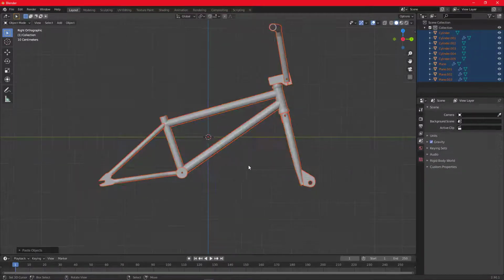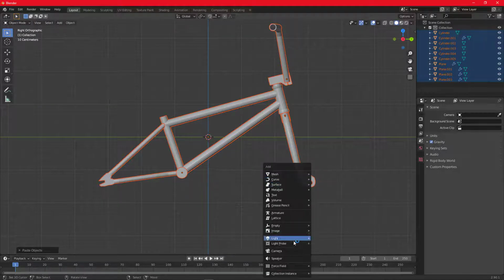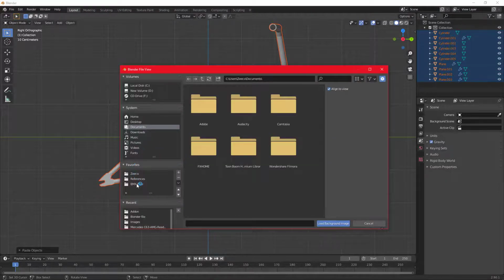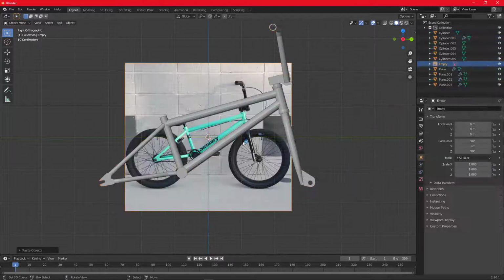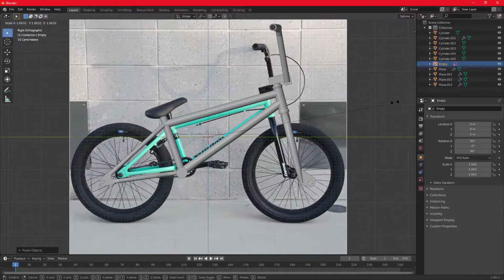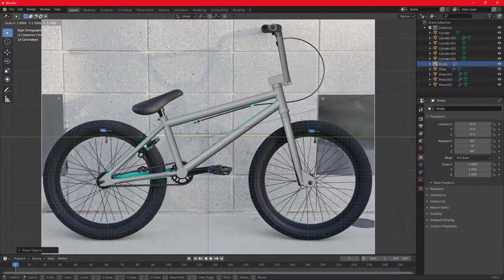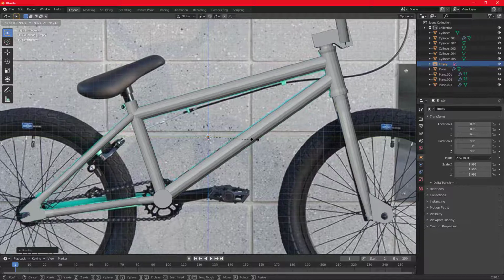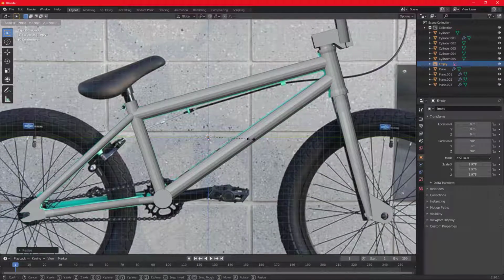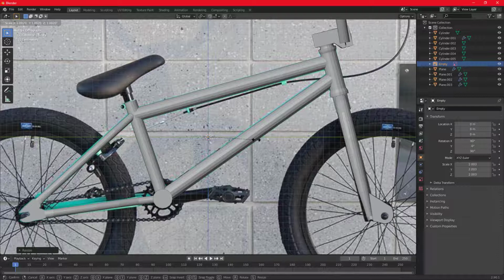and we continue with this and press Shift A, sorry, to add a new image, which is background image, and go to where you have your reference images. I think I have mine here, which is this. So now we have it here. It's not much. Just press X to scale it up until it looks perfectly okay. Yeah, I think it's okay now.